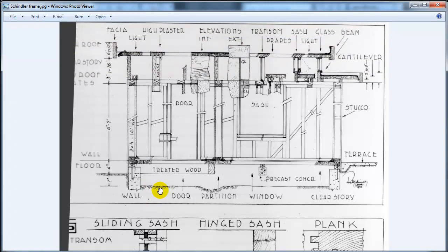We'll go ahead and have the subfloor at least 6 inches above the grade. That's typically just to allow for a water detail so we don't get water into the building. We like to basically allow that the finished floor is up above where the grade finishes off. So let's go through and start with that.